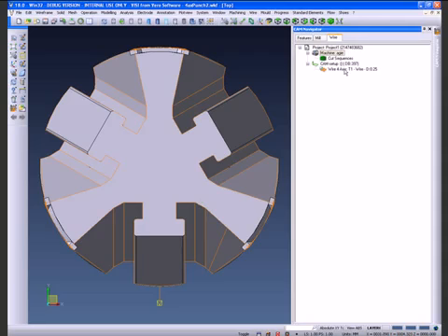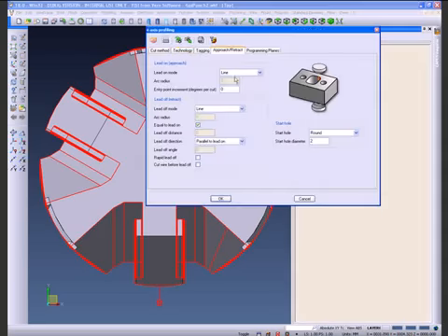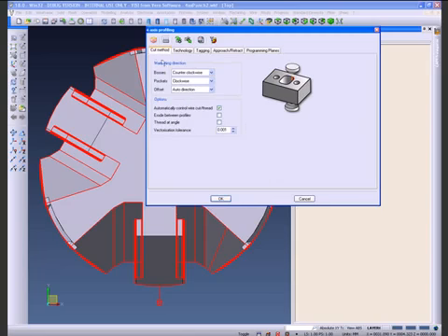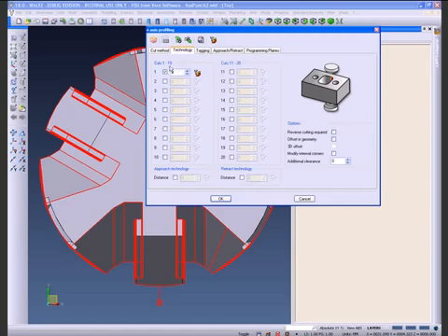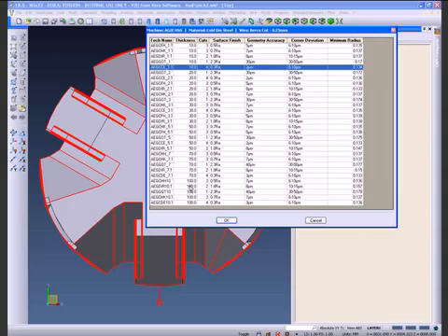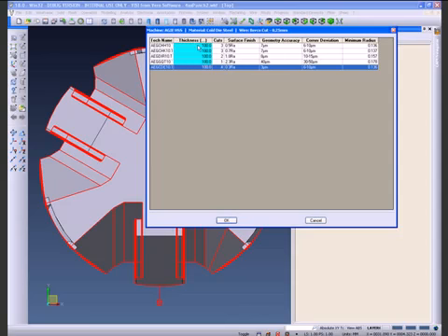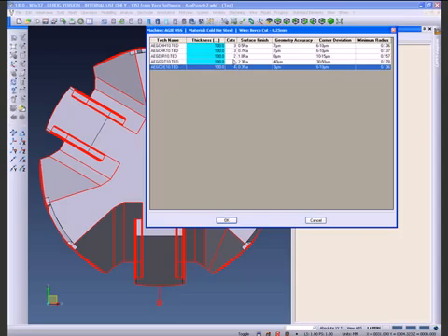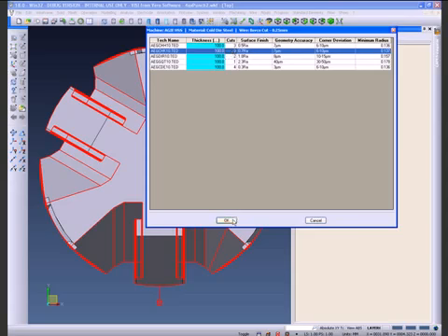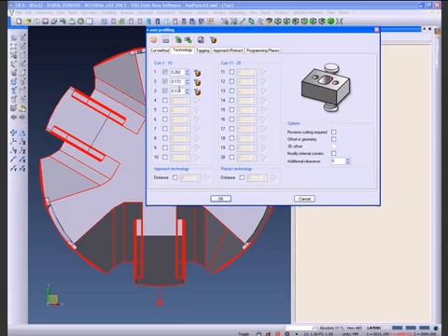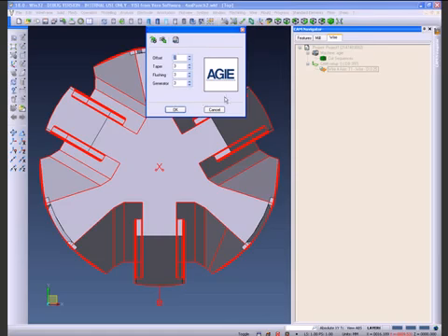The 4-axis toolpath we have at the moment has default settings. As you can see, we've only got one cut at the moment, but we can go into our technology table and apply a 3-cut, specifically for the AAC machine. We come down to the thickness of material of 100 mm. We can then go in and search for 3-cut technology. Once we've selected this, we can go into the dialog and make sure that we have the offsets and power settings specific for each of those cuts.